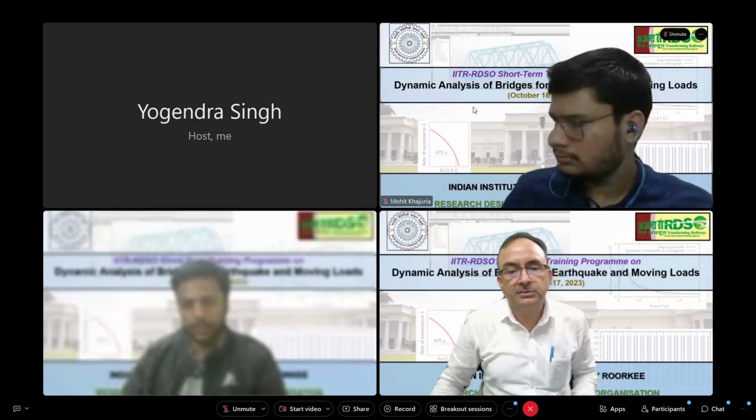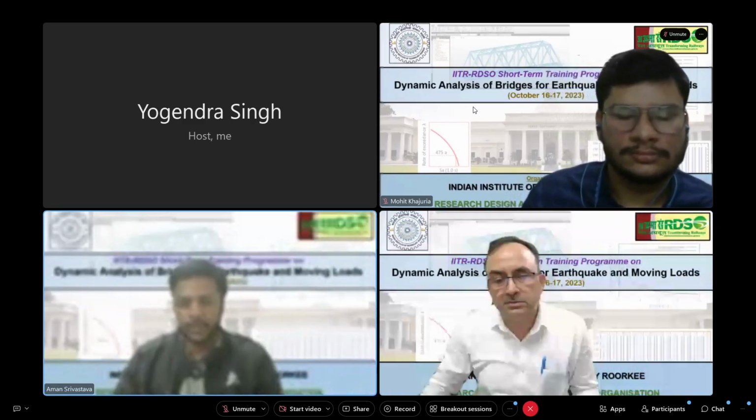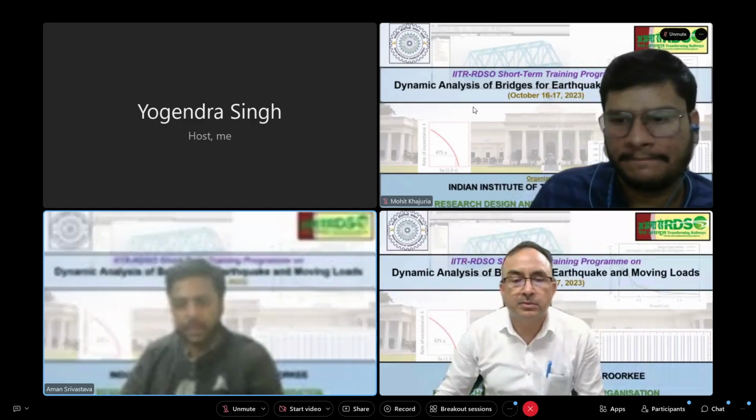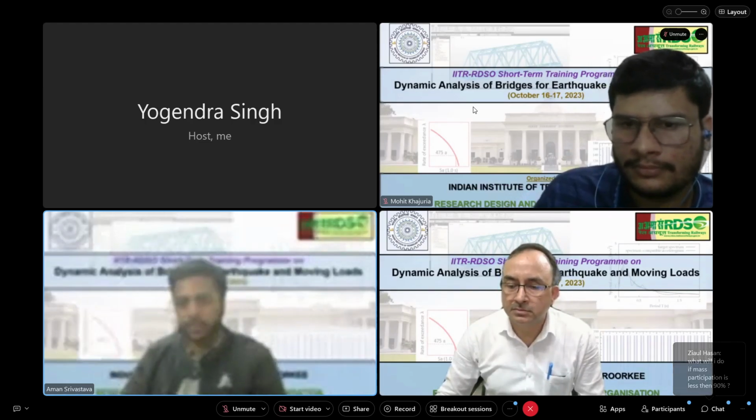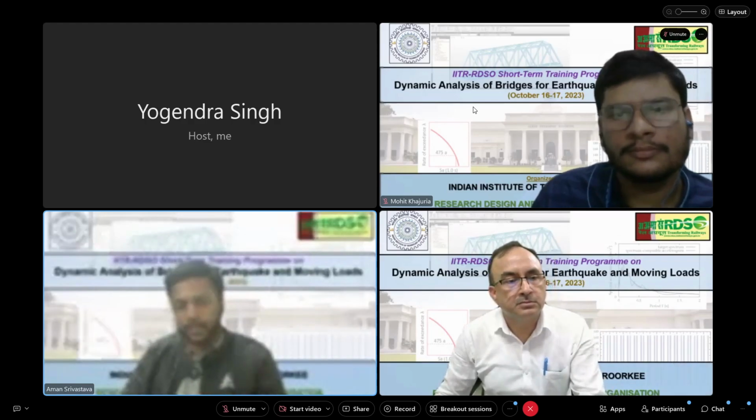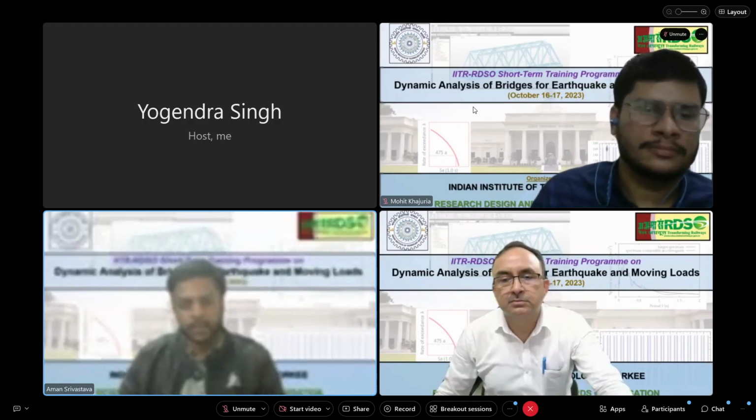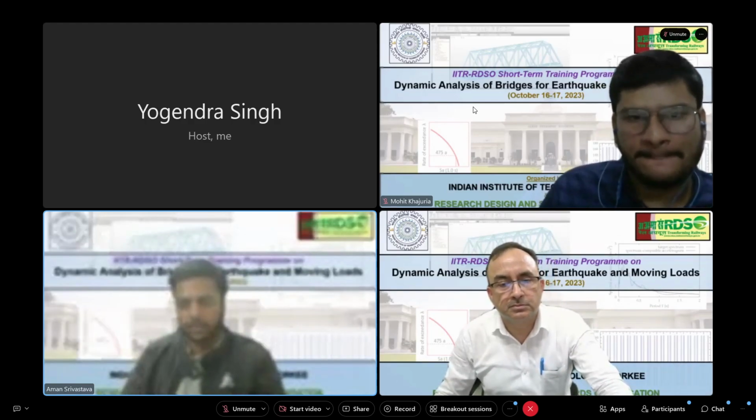Okay. Thank you, sir. Thank you, ma'am. Mr. Abhishek is suggesting something regarding his experience on modeling of composite section girder bridges. He's saying that there is some bug in MIDAS and it does not calculate IXX correctly. You have to manually input the correct stiffness scaling factor.